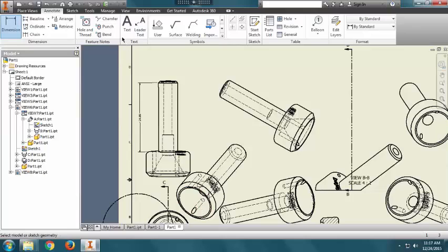So if you want to mention something like that, you can select the chamfer option here and click over the area to point out that this one is a chamfer, and then you can see that this is a hole option. So you can say that this one here is a through hole. So this one again is a through hole. It gives you even the dimension of that particular hole. So there are a lot of features here which you can use.